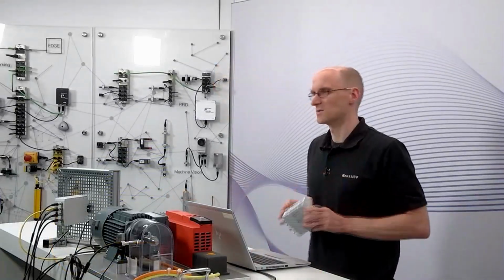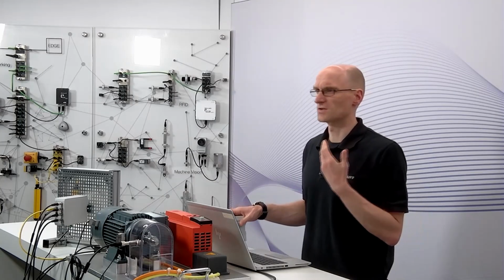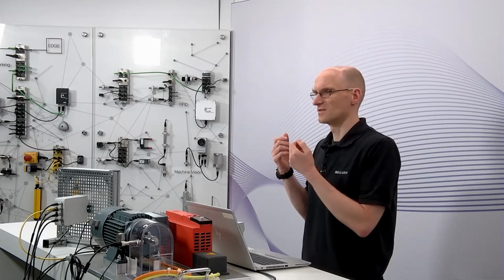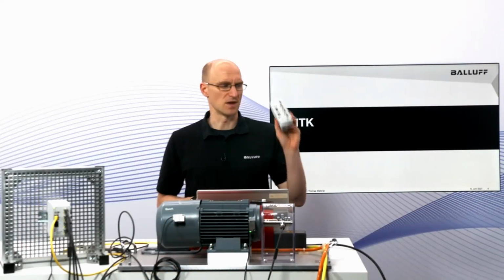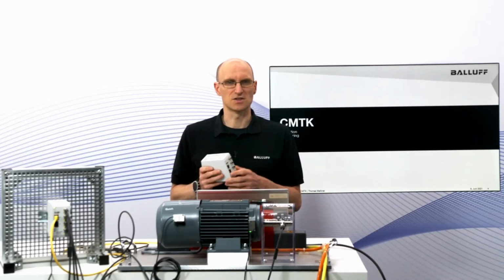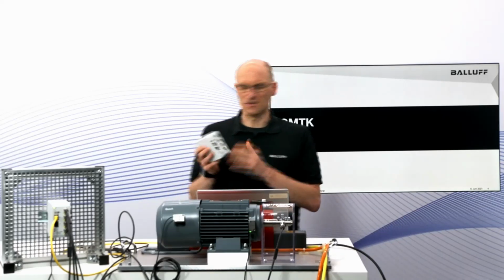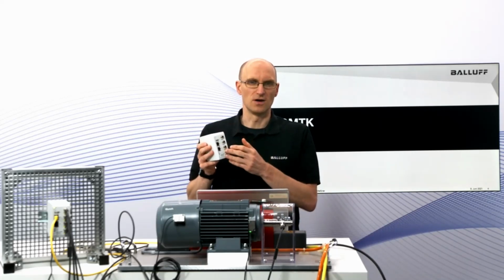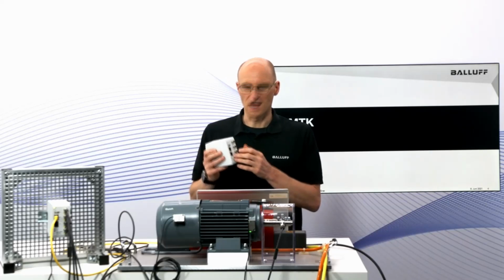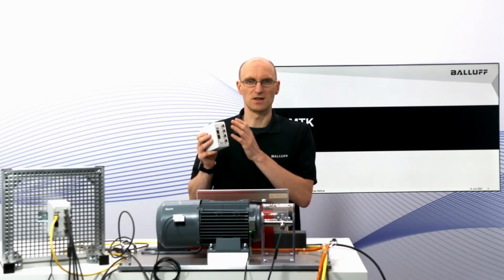And this is something that we would like to address with the Condition Monitoring Toolkit, which I have here in hand. We're trying to offer here a solution which ranges from sensors to the data aggregation and the visualization and data analysis. At the heart of the Condition Monitoring Toolkit is the base unit that I have here in my hand. So this is basically a combination of an IO-Link master and an edge gateway. The system itself is powered by 24 volts, so it has to be placed in a cabinet. You can connect up to 4 arbitrary IO-Link sensors to it, and then more notably, there are 2 LAN ports.